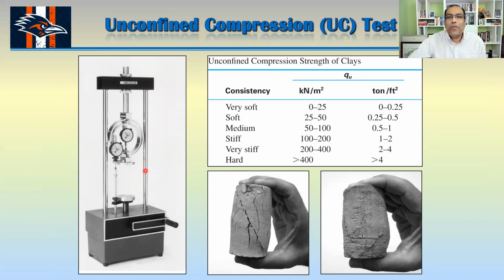So that's why soil fails in shear before reaching failure due to compression. And you can see this is the line they are trying to show you, which is actually theta here, right? The angle is theta here. Sometimes you don't see failure like this. You can just see that the soil is soft enough that it is not breaking down, rather it just compresses and makes a bulge like this.